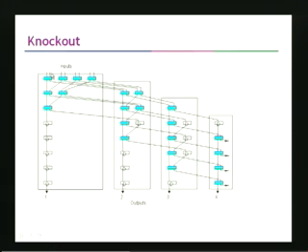Let me explain this algorithm again here. There are 8 packets, or 8 input ports, which want to send a packet to a particular output port. Our switch speedup is 4. Therefore, out of these 8 packets, you need to select 4 packets which will be sent to this port. So, how do you select that? In the first section, we have these 2 by 2 concentrators.